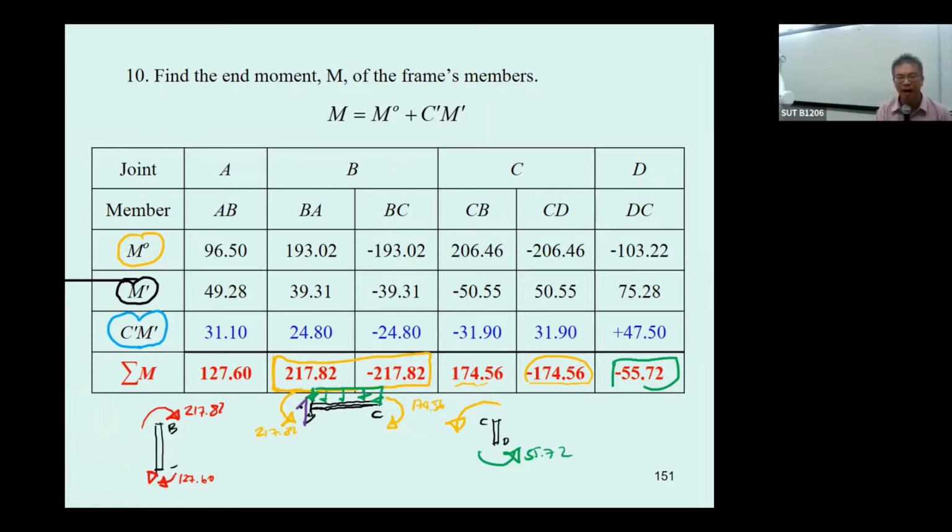And then don't forget about the applied loading that you must put into the free body diagram, and then you determine the end shear of this one. This one rotates like this, for sure this is going to be A sub X, and this one is going to rotate like this, going to be D sub X. And don't forget this load will transfer across the joint. Okay, it's going to be downward here and upward here, and downward here, and it's going to produce the A sub Y here. So you get these three as the reaction of the frame.